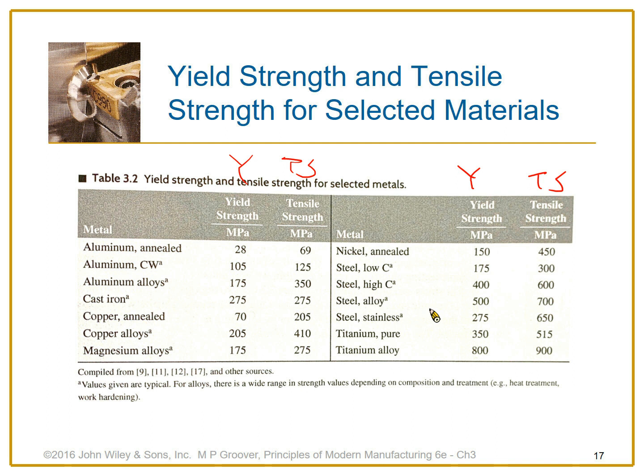For example, some materials need a huge amount of stress before they reach the plastic region. Titanium alloy is very strong, right? It takes a very strong force until you would change it to the plastic. But for some materials, for example, copper, I mean copper annealed, it's only 70 MPa and you would reach the plastic.